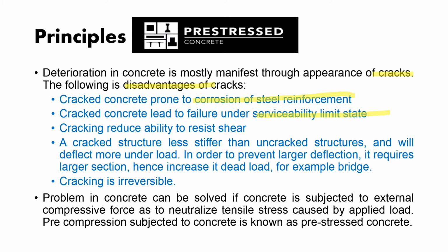And cracking reduces the ability to resist shear. Once it cracks, of course the strength is reduced, so the shear resistance is also reduced. A cracked structure is less stiff than an uncracked structure and will deflect more under loads. Once cracked, everything will be weaker, and it will deflect more. In order to prevent larger deflections, it requires larger sections, hence increasing the dead load. If you want to avoid that, a good thing is to use prestressed concrete.